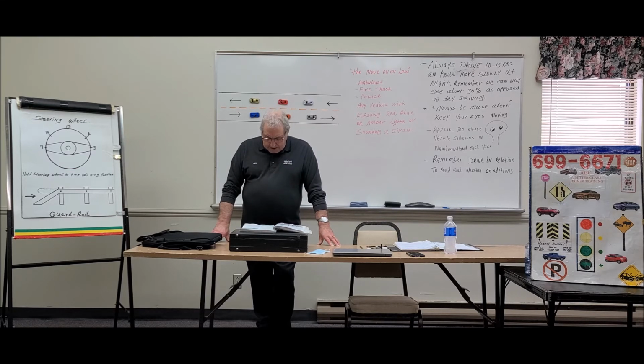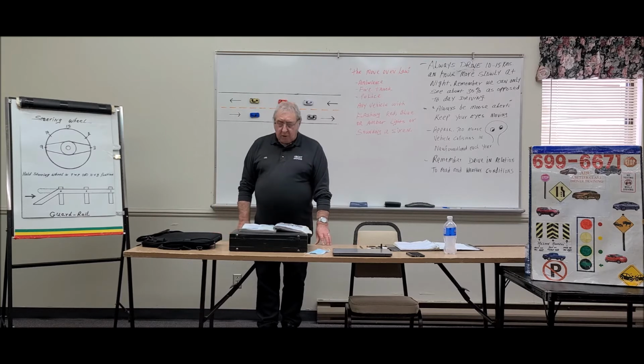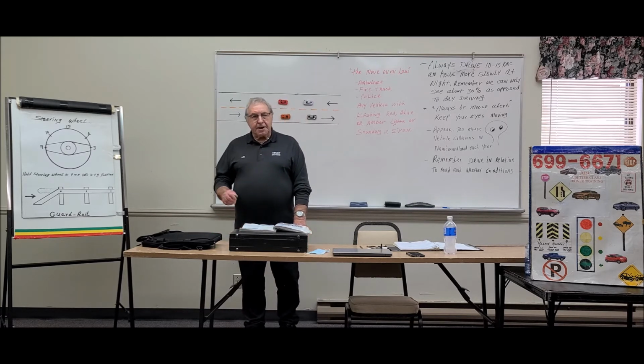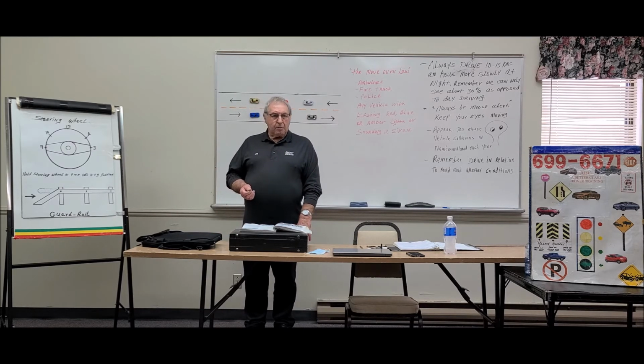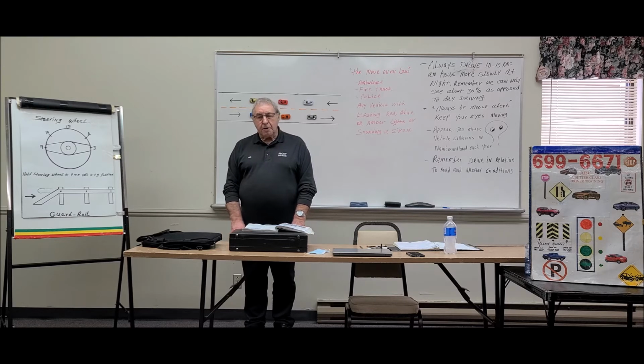The airbag is located in the hub of the steering wheel, as we have mentioned. So the airbag readiness light, of course, will come on when you turn on the key, and all the lights in your instrument panel will light up. But once the engine starts, in 2 or 3 seconds, these lights should disappear again. If they appear when you're driving down the roadway, the airbag readiness light, you should have it checked, because it's your safety or the passenger in front.